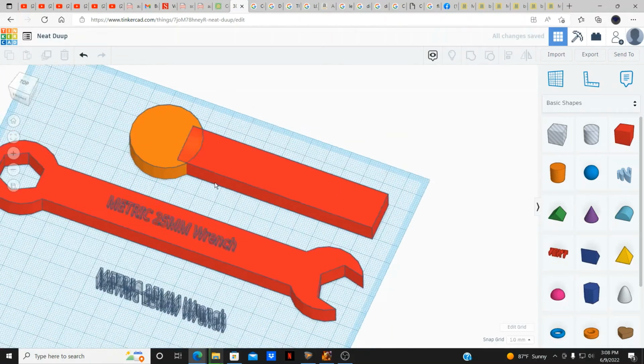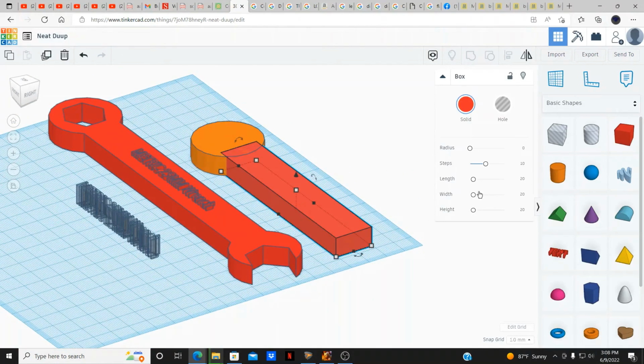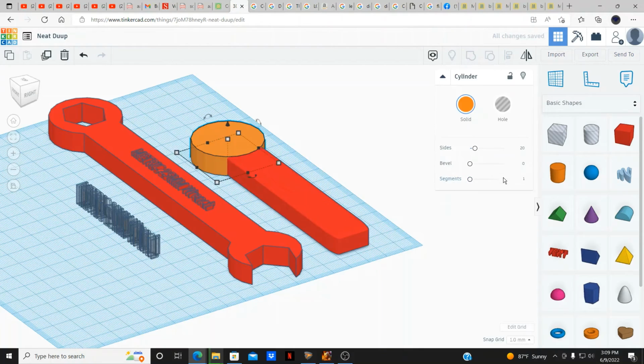So now, if you're trying to make the edges rounded, you can do that. You just go over here and type in, let's try 9. Whoops, too much. Let's do 3. There we go. Or I can do 2 as well, to make it a little more rounded. Same thing with this 2 as well, with the sides. I will bevel this right around 3 or 2. There we go. Now we have the sides right away.